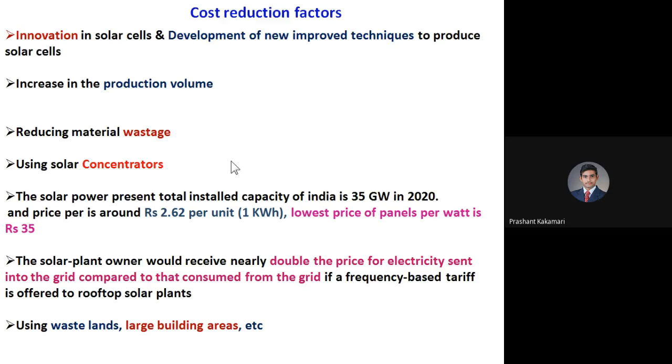Next point is, we discussed the standalone system, grid connected system, or the hybrid system. Recalling those three systems, in the grid connected PV system, the solar plant owner can supply the extra power to the grid, to the public or the government, and any little amount of power required, he can utilize for the home.